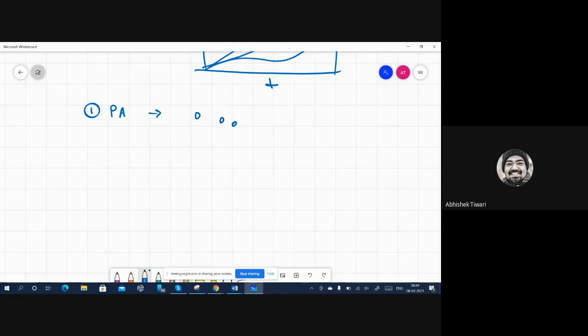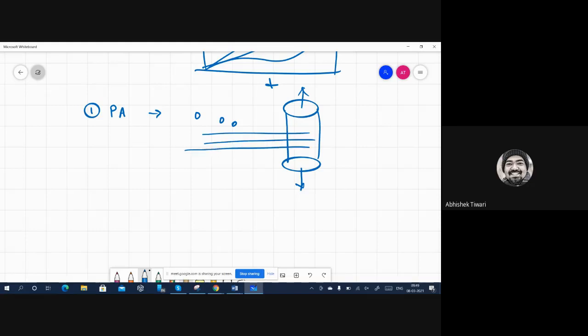So you're putting the tensile specimen in the machine, you're loading it, and you're also bombarding it with positrons, and then you're detecting the images, and you're seeing at what point the small voids started forming and at what rate their sizes are increasing, and so on.